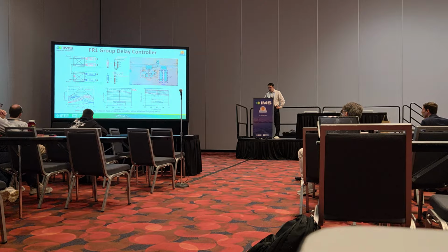So the group delay controller uses a reflection-type phase shifter, but this is not a phase shifter. By controlling the load, which is based on a resonator, when we change the resonant frequency, we're going to have a different delay. So by changing this red load, you will see this red delay. But this bandwidth is very small, and the delay varies over frequency. There's no center frequency.